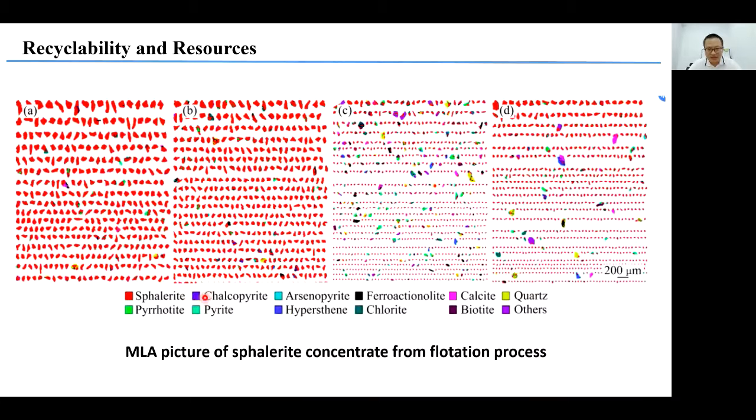But besides zinc and sulfur, we also have chalcopyrite, which is rich with copper, iron, and sulfur, and arsenopyrite, which is rich with arsenic. So you still remember I have been talking about the arsenic problem in copper making. So arsenopyrite is also available in our zinc concentrate. And also the pyrite, also calcite and dolomite. So they are impurities, or gangue components in our zinc sulfide concentrate. And our work is mainly based on this phase composition or chemical composition.